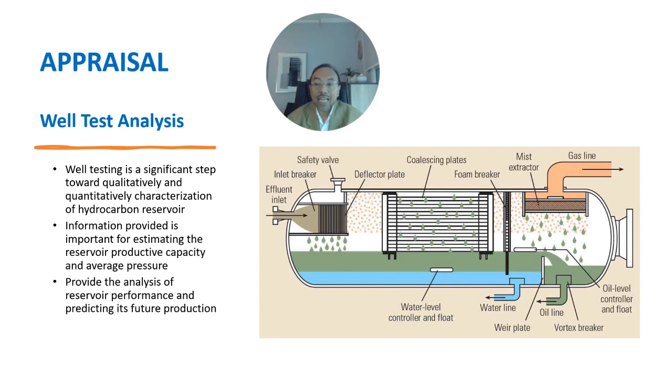Well and formation tests are also primary sources of critical data for reservoir models and are the principal means by which engineers confirm or adjust reservoir model parameters. Engineers use these models to understand how reservoir fluids, the formation and the well interact, and use that knowledge to optimize completion and development strategies.